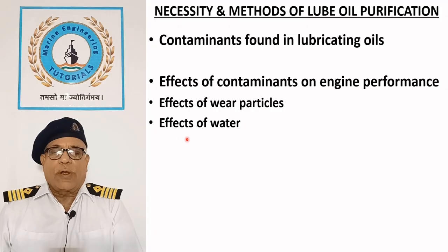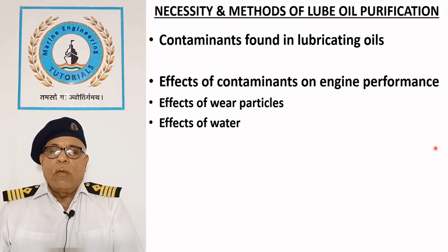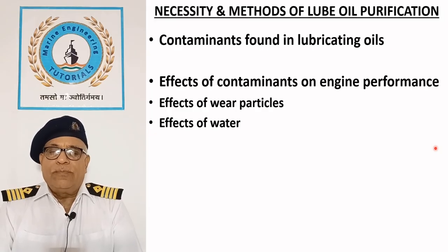Effects of water. Presence of water in lubricating oil reduces oil film strength and alters viscosity, leads to metal contact between engine parts, and increases friction, wear, and risk of seizure.